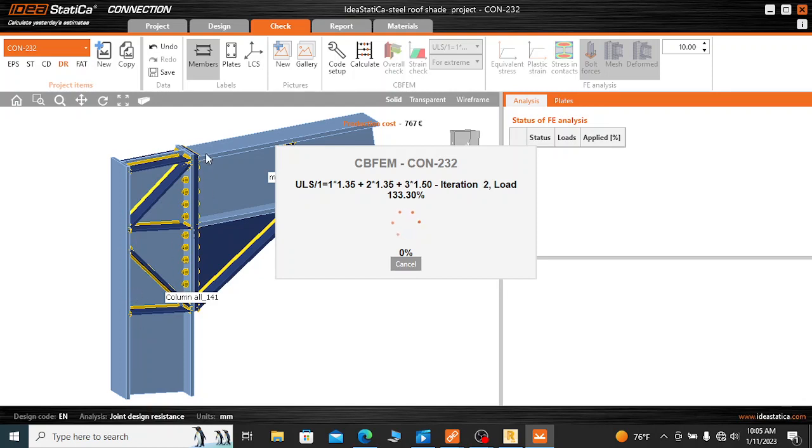because there is high moment here. A moment greater than 770 kN is exerted here at the beam as well as at the columns. So that is why more bolts are being used here. And now, in order to increase the resistance of the connection, we need to use the bracket here, because there is high moment here.